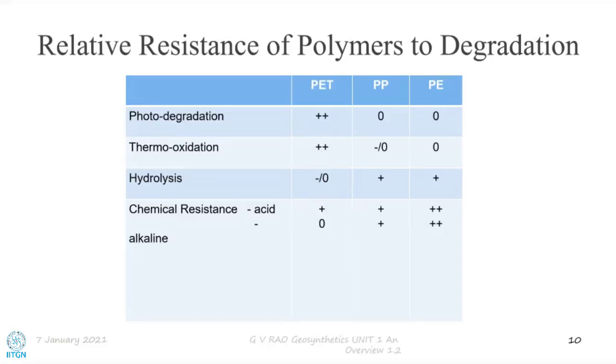But more importantly, we require a certain grade of molecular weight. If you are using polyester, we require a certain molecular weight. The molecular weight we are going to look for is something like 20,000 or more. If the polymer has a lesser molecular weight, it's not going to be suitable for us.